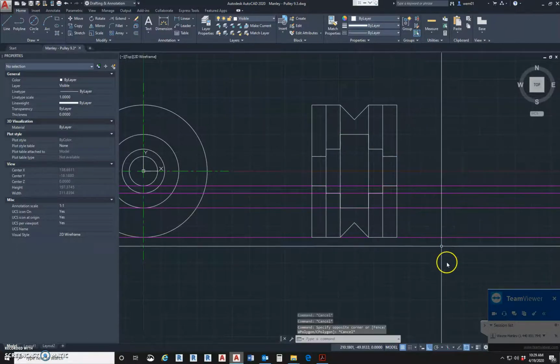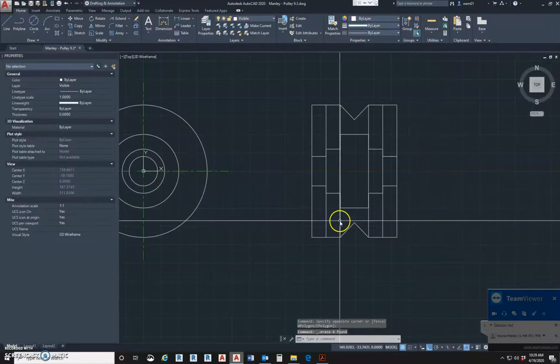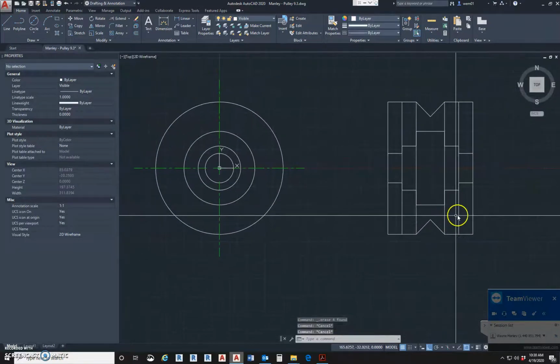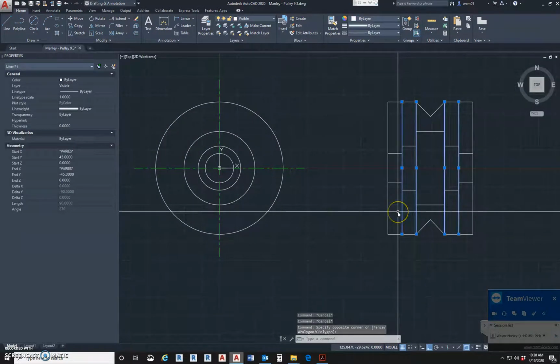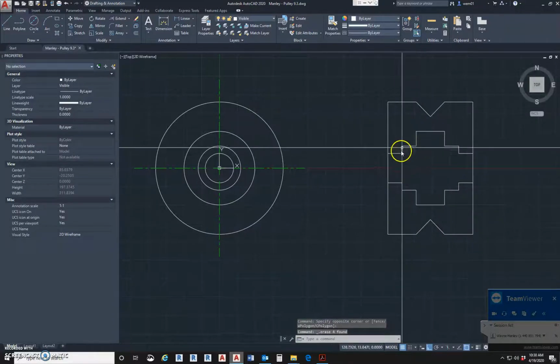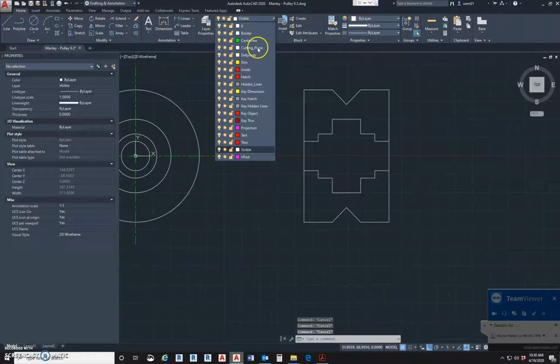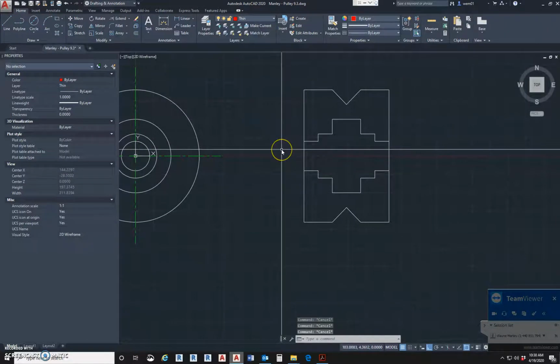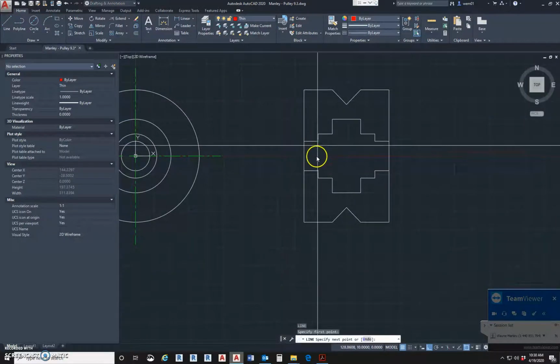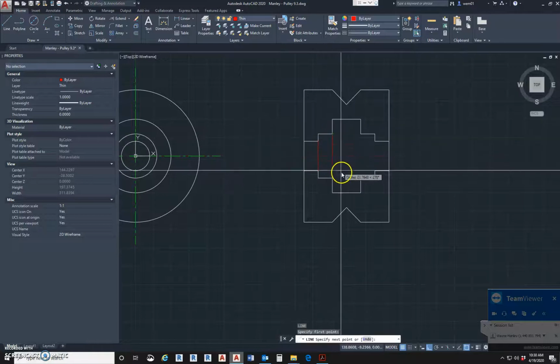There we go. Then I'm going to get rid of all these projection lines. Okay. And then I'm going to get rid of these lines because these went continuous through. And I drew up and over. So that's pretty simple. Now we're going to change to thin lines. And we're going to just draw here, to show the lines beyond.